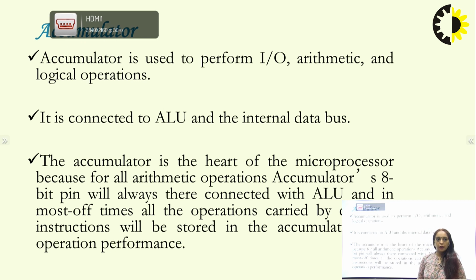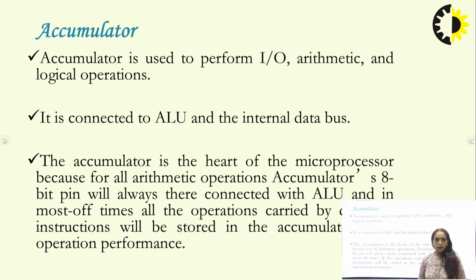So next we have accumulator. Accumulator is used to perform input-output operation, arithmetic and logical operation. It is connected to ALU and the internal data bus. The accumulator is the heart of your microprocessor, because whatever instruction we are going to execute, one data should be placed in accumulator, and all the arithmetic and logical operations by default work on accumulator, and the result will be updated in accumulator.